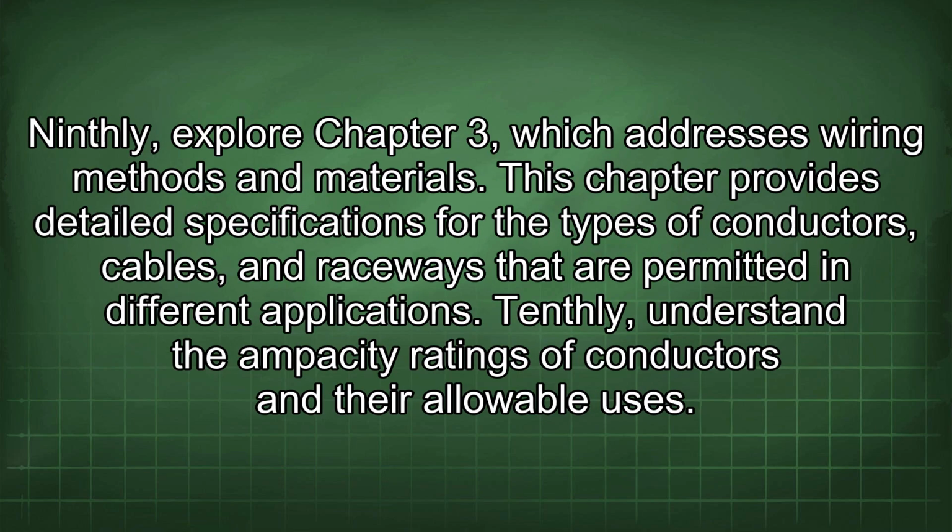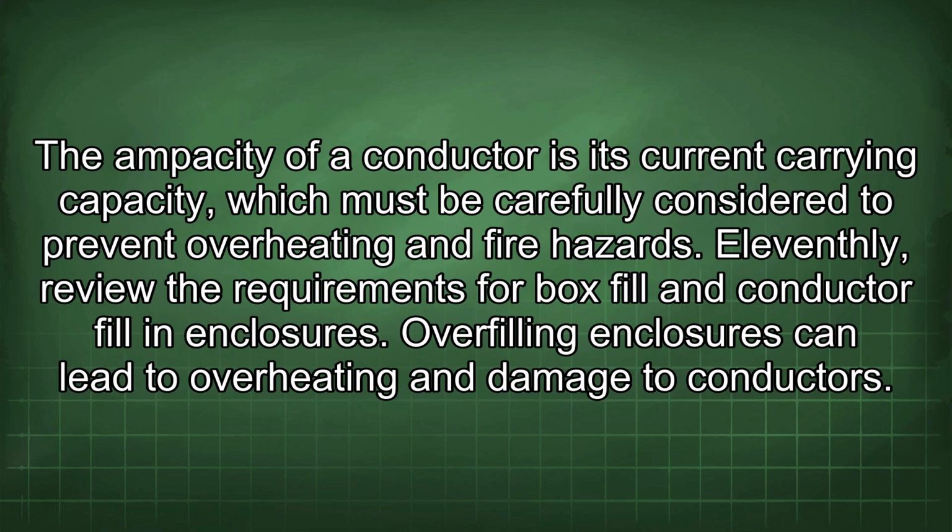Ninthly, explore Chapter 3, which addresses wiring methods and materials. This chapter provides detailed specifications for the types of conductors, cables, and raceways that are permitted in different applications. Tenthly, understand the ampacity ratings of conductors and their allowable uses. The ampacity of a conductor is its current carrying capacity, which must be carefully considered to prevent overheating and fire